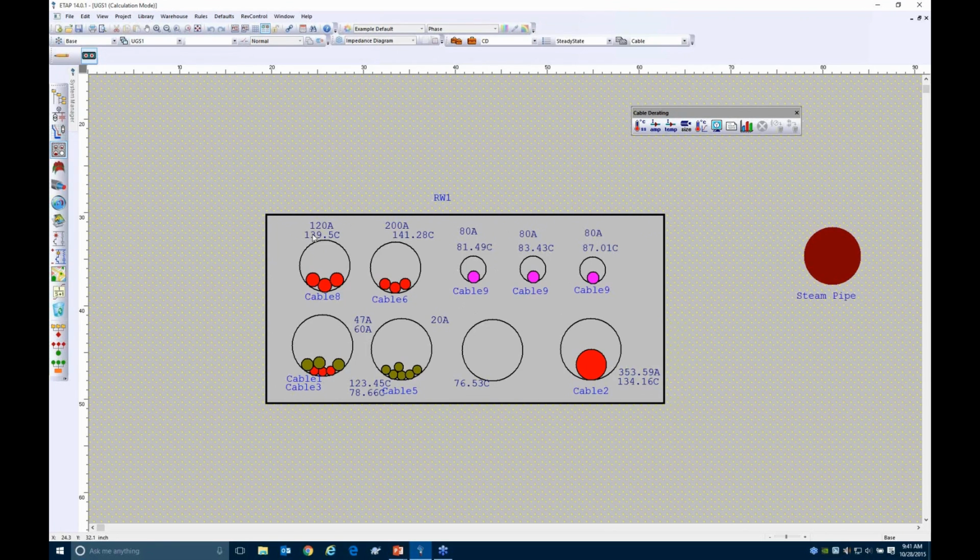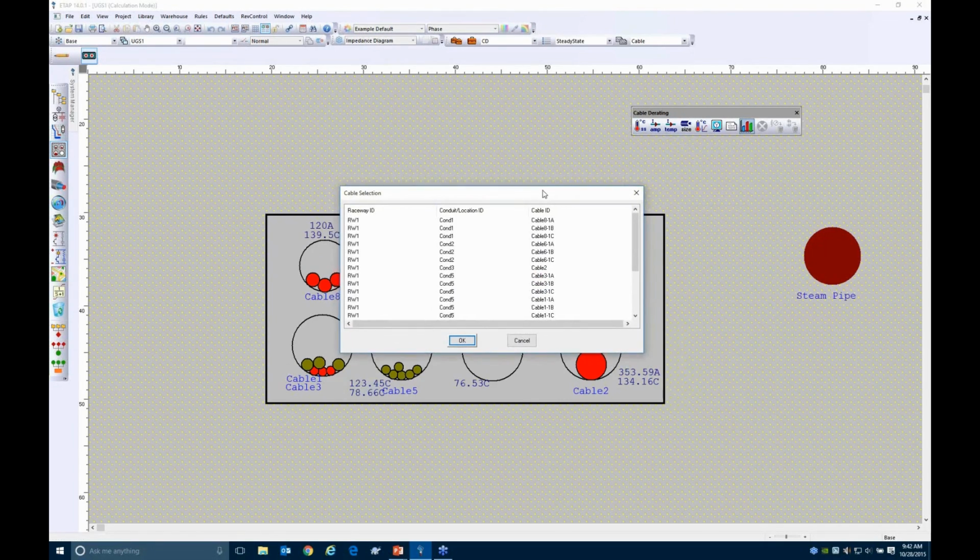Now you'll notice that these results are a little bit different than our steady state value. So I'm going to go ahead and run steady state again, 73. I'm going to run this one. You'll notice it's 139. I ran a transient temperature calc. It's load as function of time. So what temperature am I seeing here? This is the worst case temperature that was achieved during that load profile. So that's really what the result's telling me, that if my emergency rating was 133 degrees Celsius, I exceeded it for this conductor. So let's see, when did that happen?